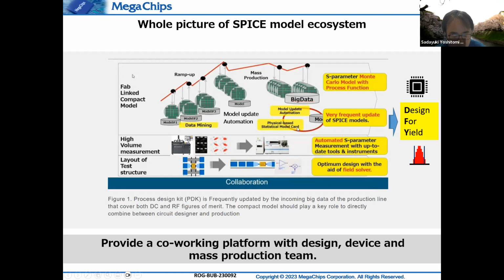The first key issue is to track the silicon performance in the form of SPICE models as frequently as possible. This fast tracking system represents this iteration cycle in this figure. In addition to the conventional DC characteristics, as is always run by the usual ASIC foundry, this system can also monitor the high frequency characteristics associated with S parameters, as shown in this GSG test structure in this picture.